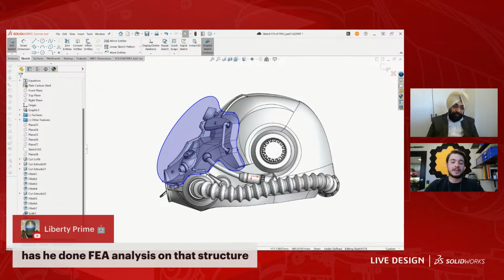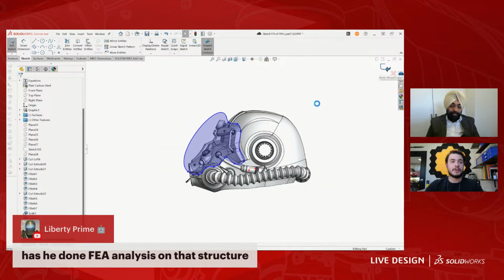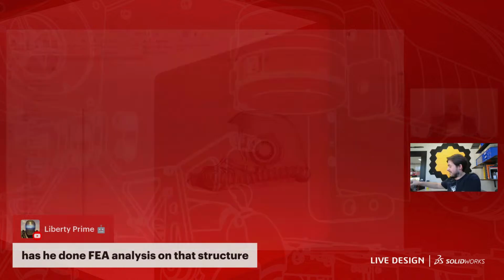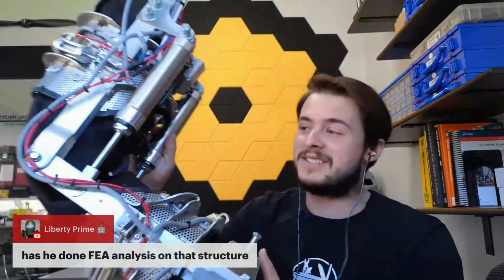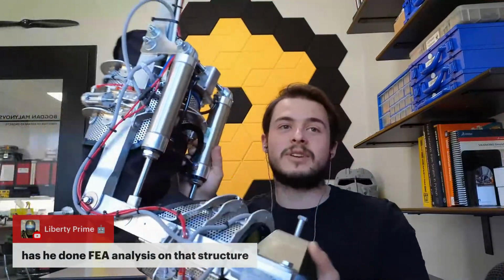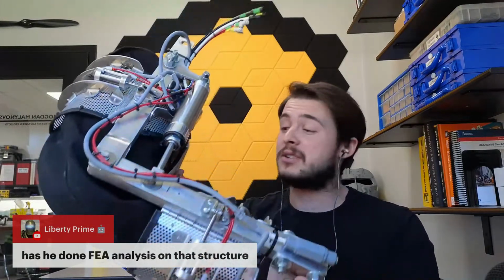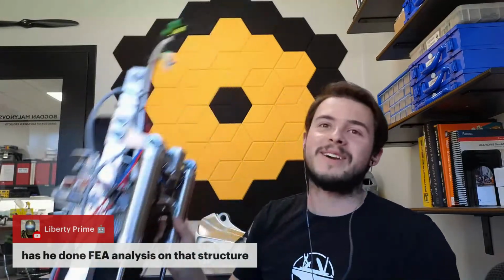Yeah, absolutely. And that allows us to create some pretty complicated geometry and work with this complicated geometry without having to use things like surfacing. I believe there's a question about FE analysis on the structure. The arms have been through FE analysis. So these things here, we did run a full stress analysis on them, and they have a factor of safety of like 8 to 1. So more than good enough.